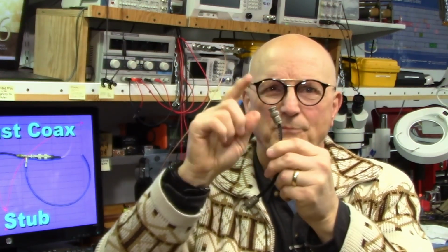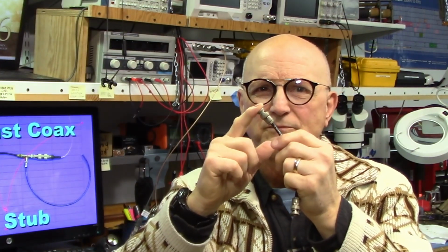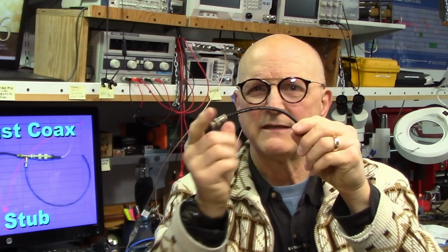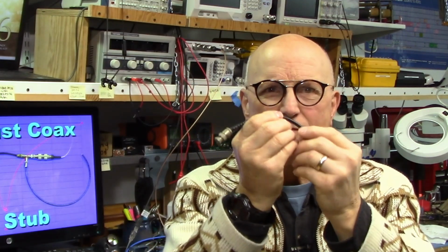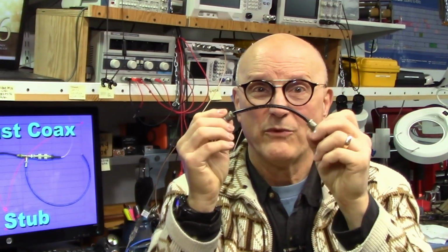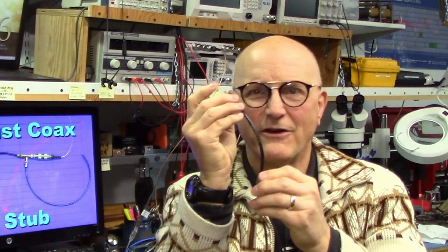This means that the impedance at that end is some very low value. Now, let's track the impedance as we move down this piece of coax at a particular frequency. When we reach the place along this coax where the electrical length is 1/2 wavelength at the particular frequency in question, the impedance at that point is the same that we started with, a very low value, nearly a short.